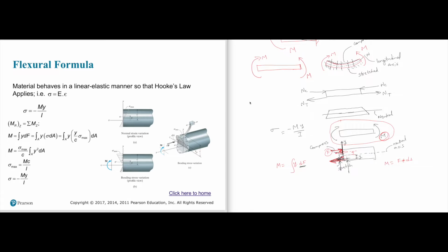So moment is nothing but this y times df, right? And df, we can write. What is force in terms of stress? Isn't it sigma times dA? So can we write moment as integral of y times sigma times dA, right? And sigma can be written in terms of the maximum stress.